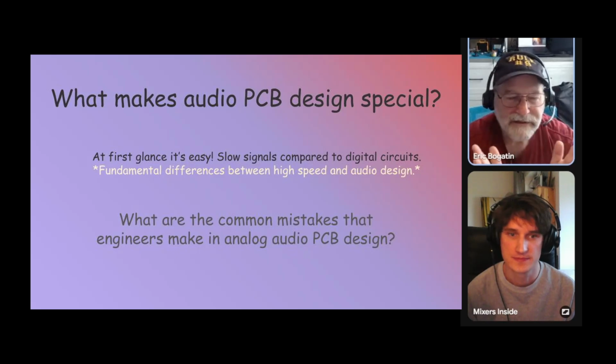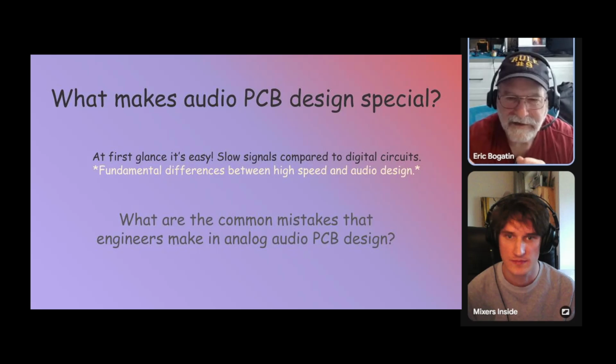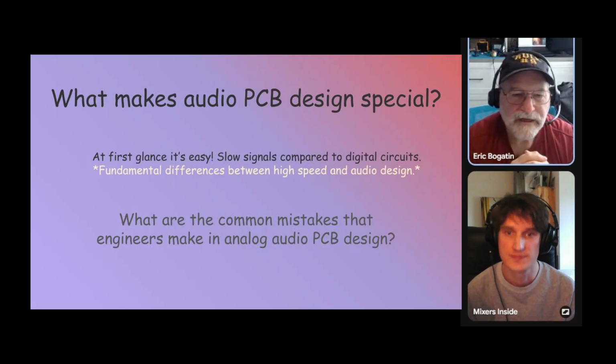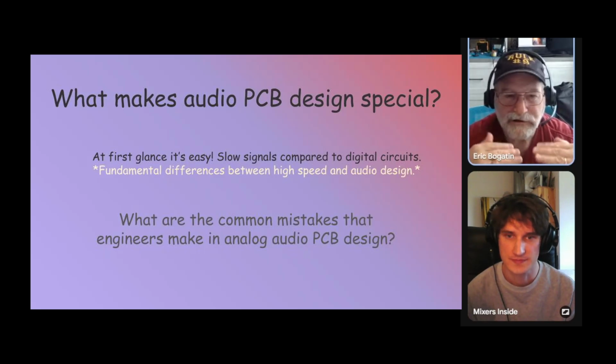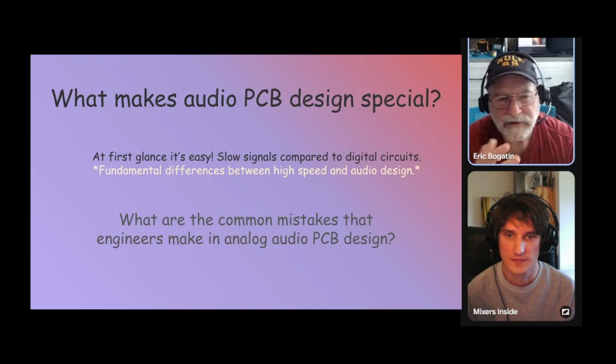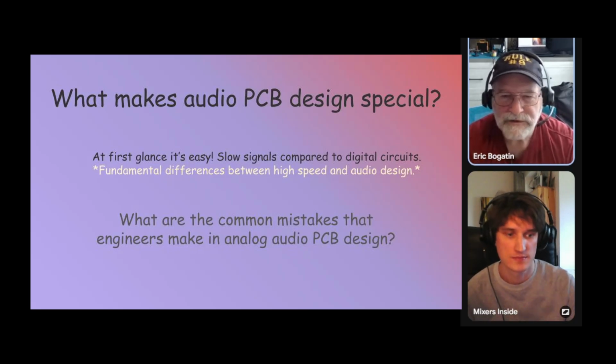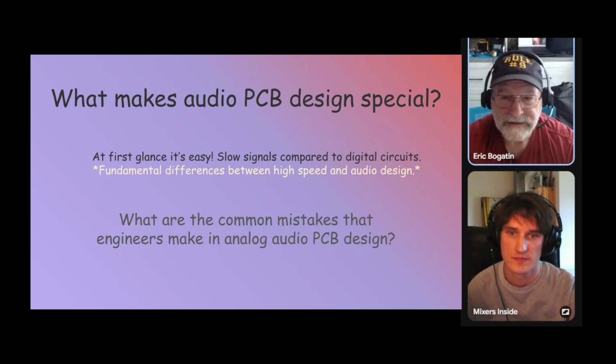So it doesn't scale with frequency. It's not like inductive or capacitive crosstalk, which both get larger with higher frequency. It's DC to 100 kilohertz. It's IR drop. And so one of the differences is where those return currents flow. It's different at audio frequency than at high speed.